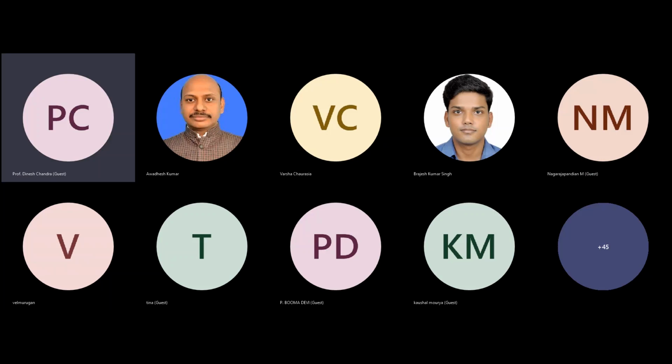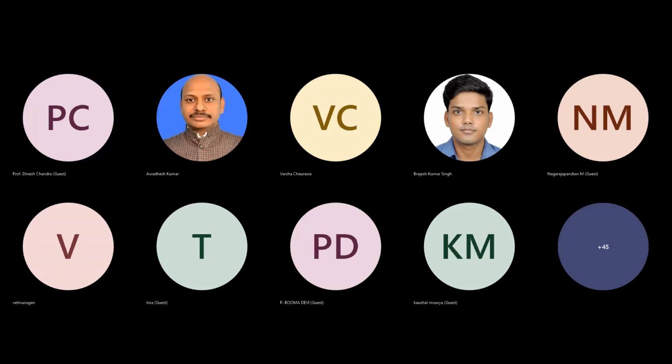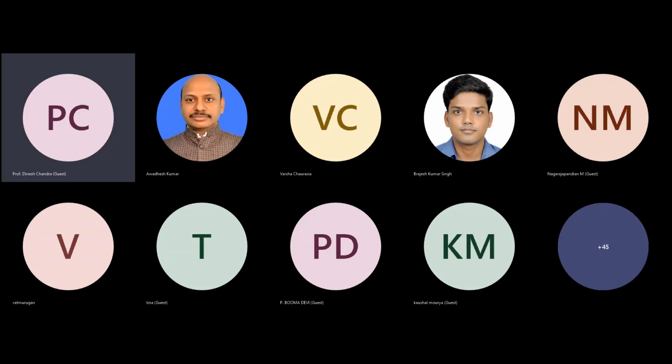The main advantage of this truncated balance method is that the reduced order model is also balanced and a minimal realization. The stability is preserved in the reduced order model. It is well known that only the balanced truncation method is fully automatic when a requirement on quality of the reduced order model is given, right? The existence of a priori knowledge of bound allows the automatic choice of reduced order model.